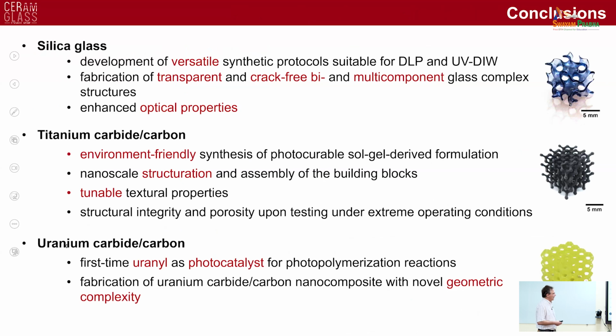So in conclusion for this part concerning the sol gel fabrication, I can say that you can use sol gel formulations for making oxides. We were interested specifically to fabricate silica glass. Again, if you try to obtain silica glass from sintering of particles, you will not be able to obtain transparent materials unless you use colloidal silica.